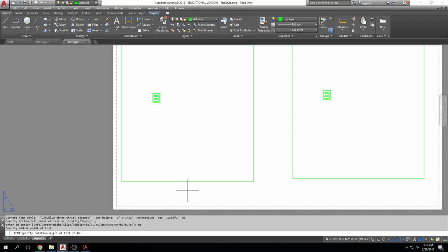So if you look at all these drawings over here, well, these are kind of small. Can you get a floor plan up here? This is a good example. You guys, it's a little small, but you can see that all of this text, the title is one size, and the text underneath is a secondary size, right? But it's all consistent, right? And if you look here, the same thing. These are kind of small, but you'll see here on the floor plan, all of these are the same height. And if we had two different viewports, you'd still want all of these to be consistently the same height, right? So it's easily read.